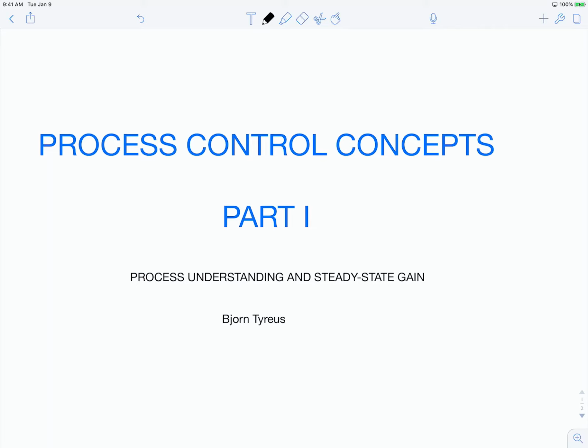The approach I'm taking in this series is to teach process control by examples using dynamic simulations. These simulations are written in the programming language Swift, primarily so that they're easily converted to iPad apps. The app I'm using for this video is the Control Concepts app, and it's available for free on the App Store. There are 3 major aspects when approaching any control problem, namely the process understanding, open loop dynamics, and feedback control. In this video, we tackle process understanding and derive some useful information from steady-state calculations.